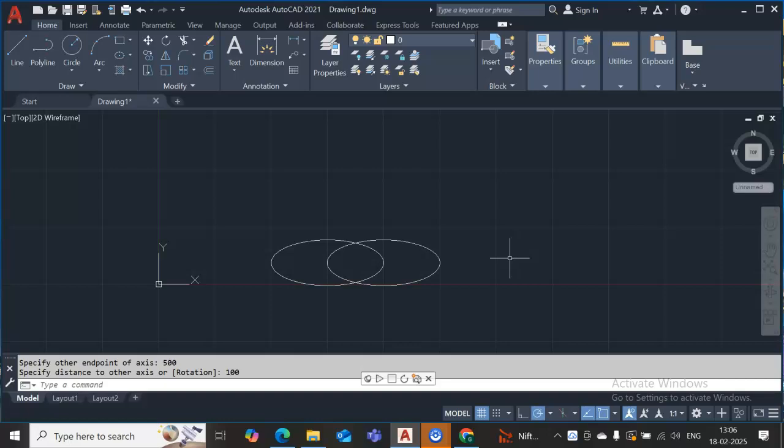Fine. Okay. And again, another ellipse option is also there. Ellipse method. Okay, another option is also there, that is the center related. So then choose the C. What do they ask here? Specify the center, not only the end point. So specify the center. This is the center, for example. Now specify the end point of the axis. So this point is there. That value is 500 again.